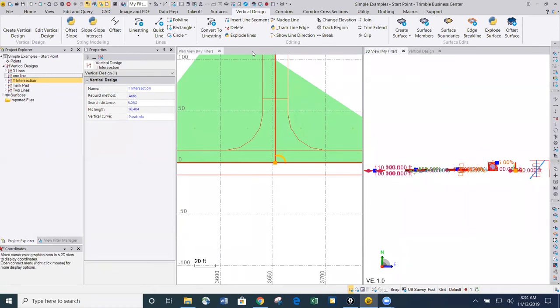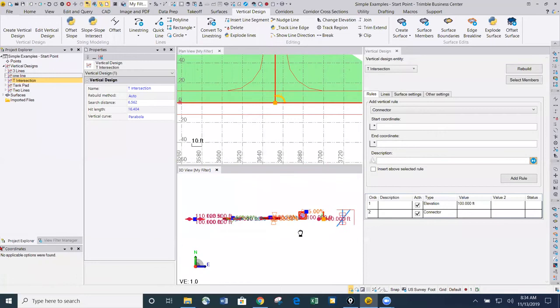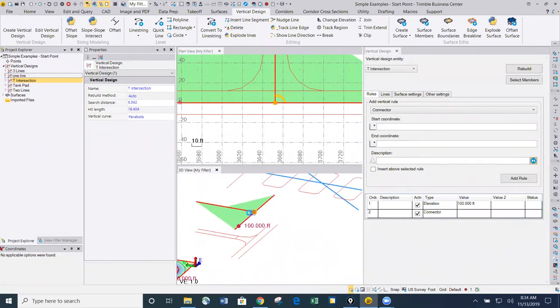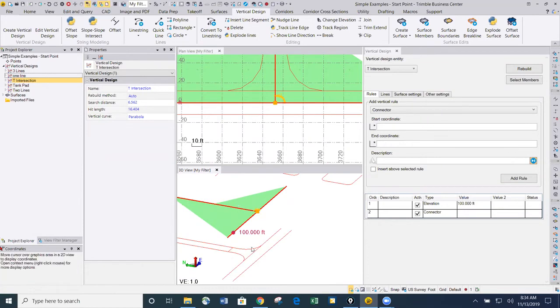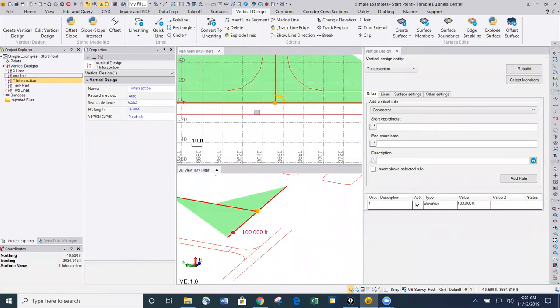And let's move that over here. Let's make that. Let's find that intersection here. So as soon as I made that connector, this line, if I just undo what I just did a second, you can see it was 2D before, and now I've elevated it and made it 3D. By making that connector, it locks in this point.